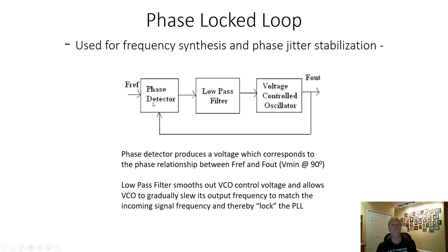And it consists of three main parts, this one does anyway: a phase detector, a low-pass filter, and a voltage-controlled oscillator. Okay, now the VCO could be something just like that programmable unijunction transistor circuit that we just showed.